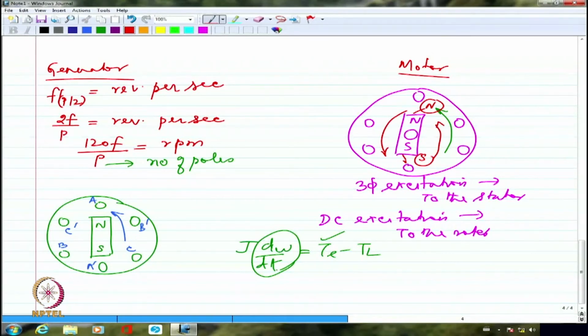We try to get it up to speed close to synchronous speed, and then we say, here you go, go and lock with the revolving magnetic field. That is the way synchronous motor is generally started. So synchronous motor has one major negative point, that is, it is not self-starting, especially if I am trying to start with 50 Hertz.